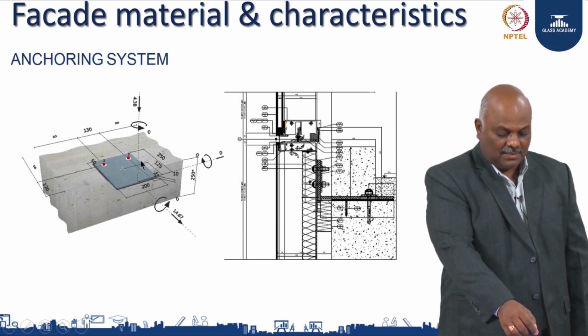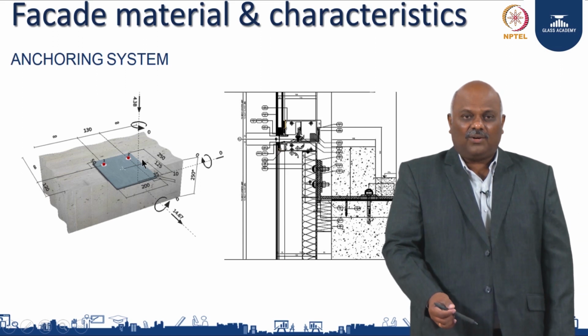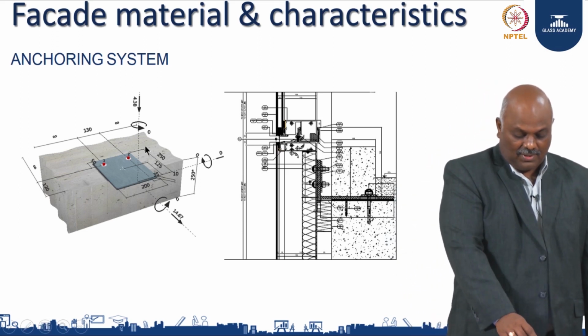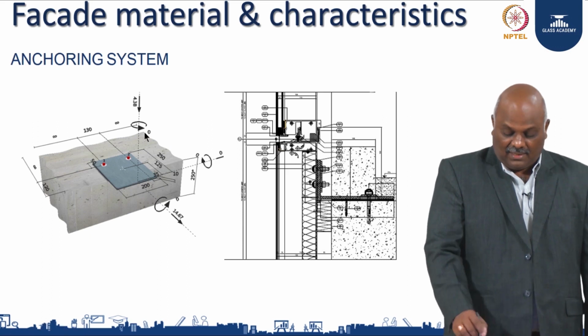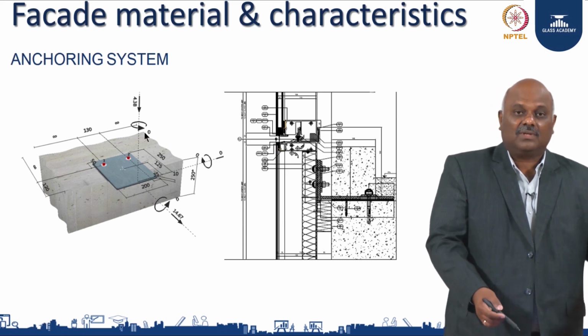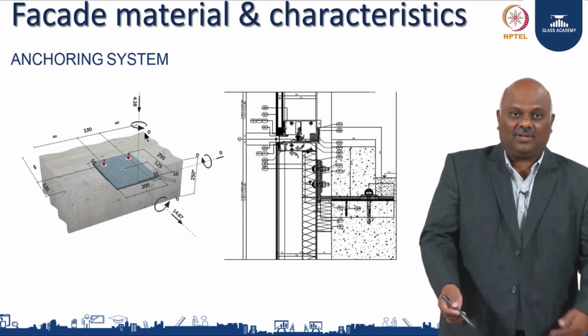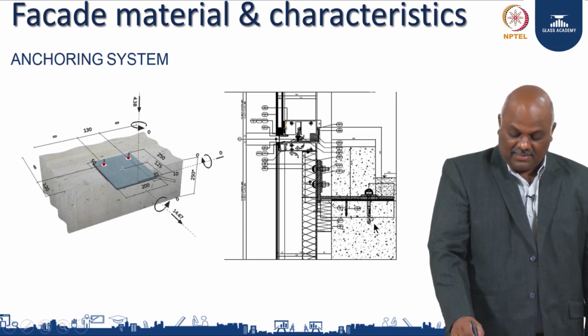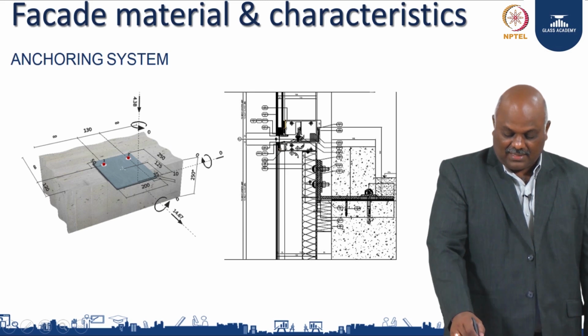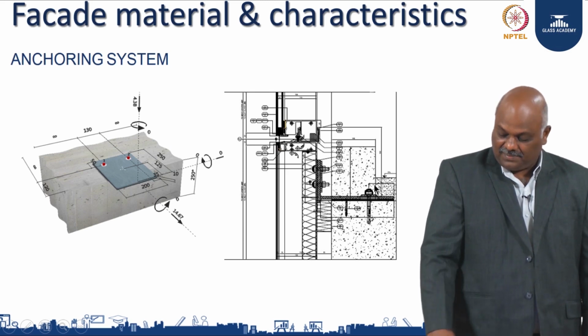Of course, you have certain factors to consider, and how you control them is based on calculation. The engineers will be doing it. There are limitations, of course. You can't place it too close to the edge of the concrete. Here, what you see is anchoring to a concrete. Similarly, here the whole system gets connected via these bolts.